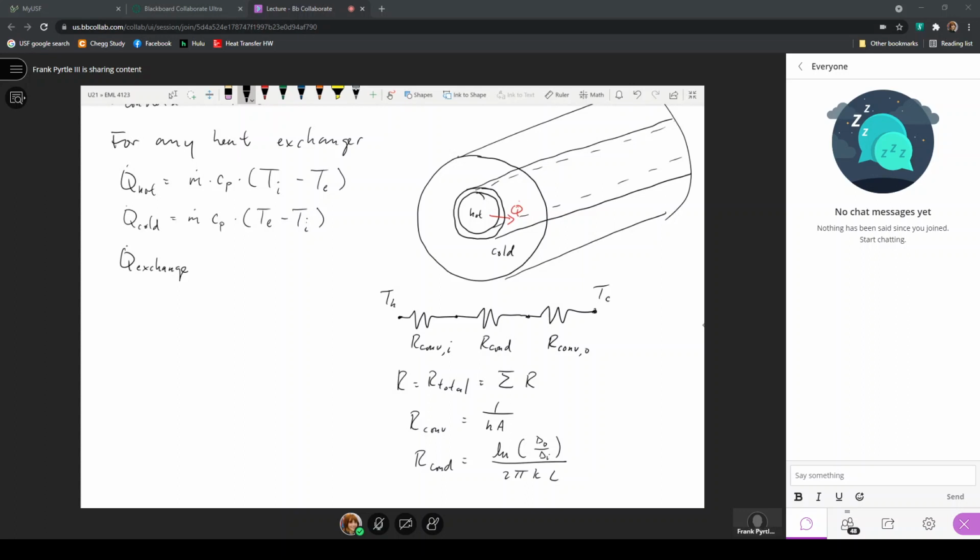And we didn't cover annular flow, but the cold fluid is also moving through a confined tube, and it will have a thermal entry region length and eventually get to a thermally fully developed condition. So its heat transfer coefficient will also be changing as a function of position.